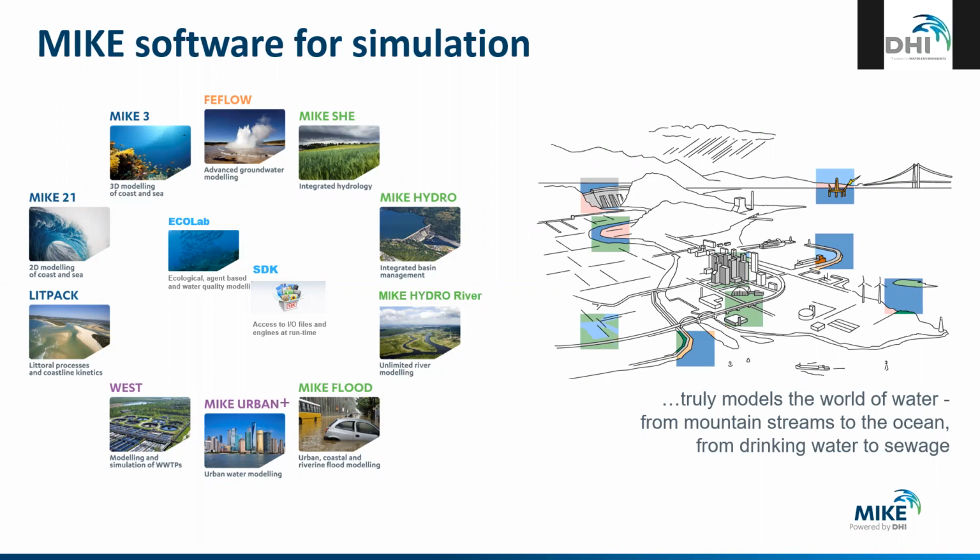And so just moving across to West. West is our wastewater treatment plant process simulation software. And West and Mike Urban can be coupled together so that you can simulate the dry weather and wet weather inflows into your treatment plant using Mike Urban Plus over a long period of time or event-based.